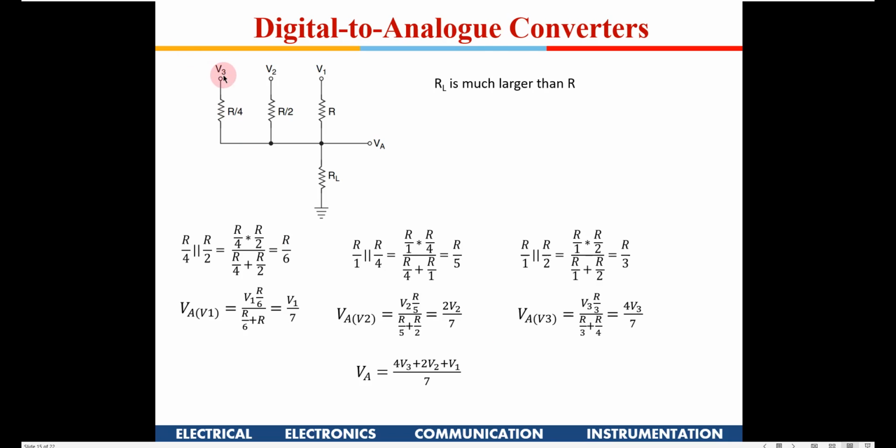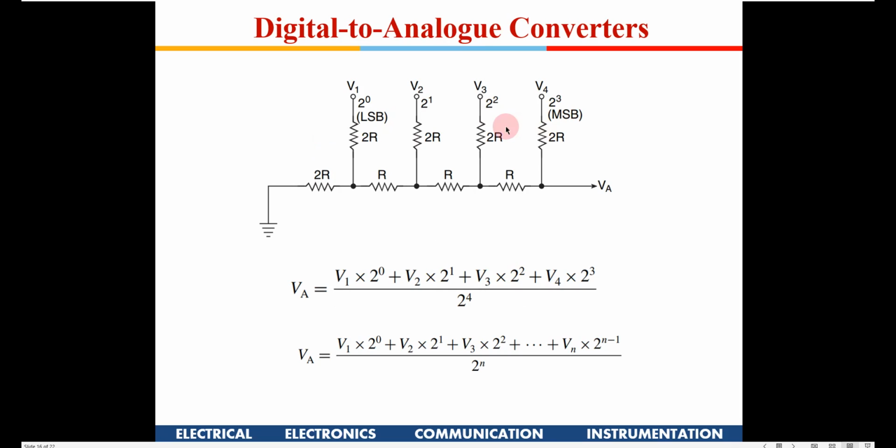It is like binary to decimal conversion. So this exactly does that. You have a binary input, and each of them has its weightage out here. So binary to decimal conversion is nothing but digital to analog conversion. This circuit exactly does that. Okay, so this is how a DAC works. Now you could